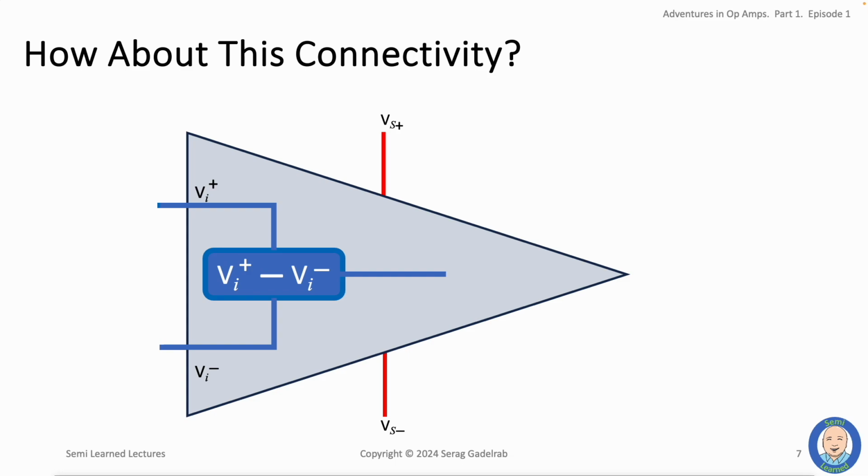If we were to connect the faint input signal to the positive input terminal of the op-amp and at the same time tie the negative input terminal to ground, what would happen? Since the ground is always at 0 volts, the faint signal is not modified by the subtraction and shows up unaltered at the output of the subtractor. Now that signal, which is identical to our faint input signal, is ready to be amplified.